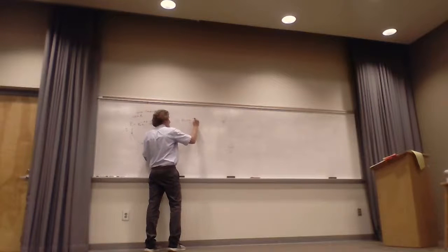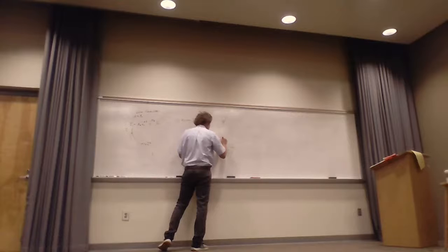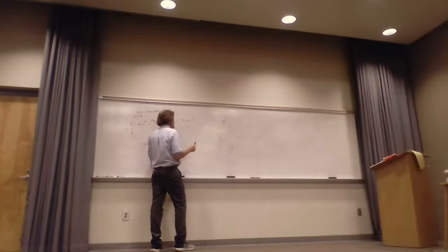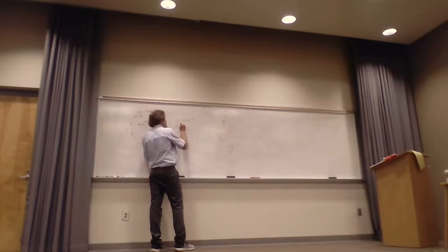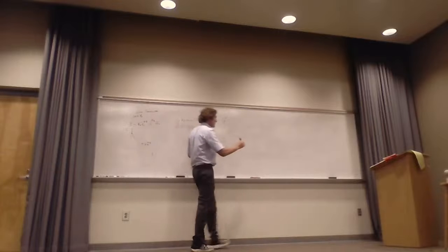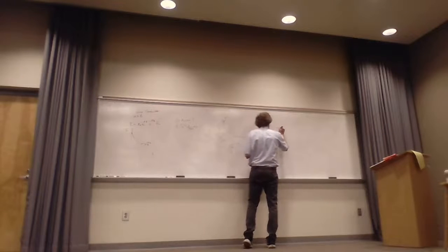You assume a current I flowing there, coming back here, and it's flowing and it's equally distributed across the cross section. Second thing is you get J is equal to I over pi a squared, over the cross-sectional area, and it's going to be in the a_z direction. You're going to make this Z, right?